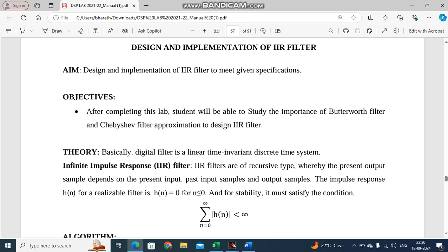When it comes to the characteristics of the Butterworth filter, it does not have ripples in the passband or stop band, meaning it has a smooth flat response up to the cutoff frequency. The higher the order of the filter, the sharper the cutoff between the stop band and pass band. It's also used in a variety of applications like audio processing, data smoothing, communication systems, and various domains where clean signal transmission is critical.